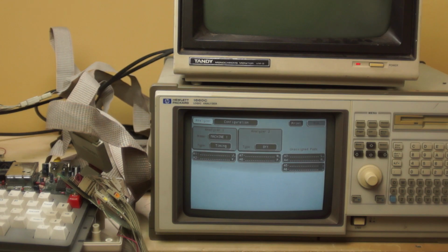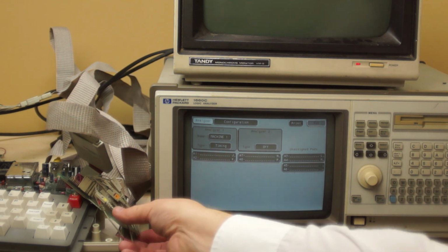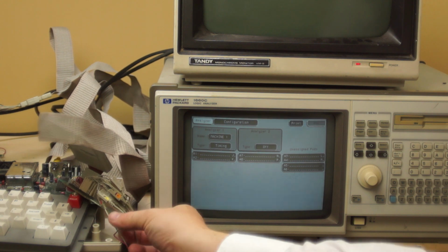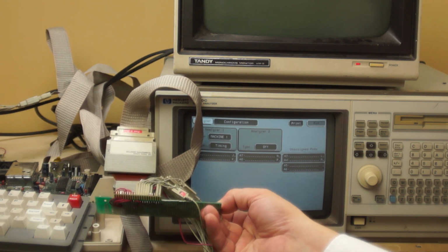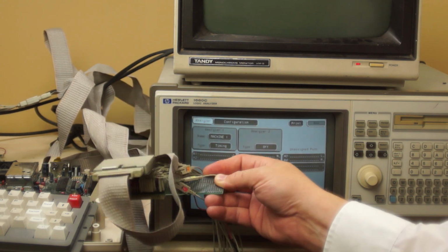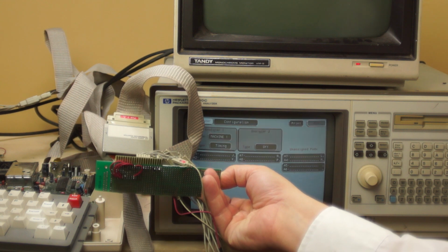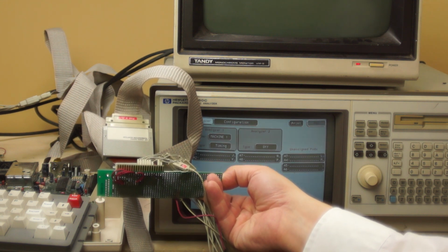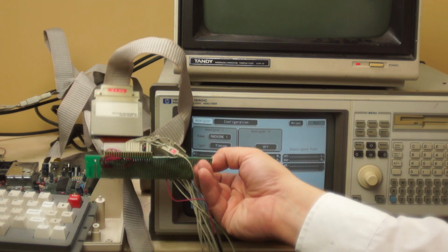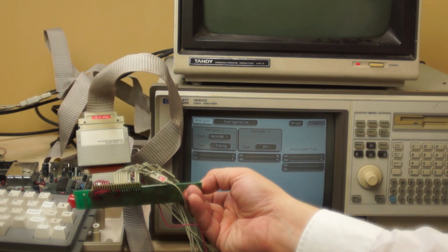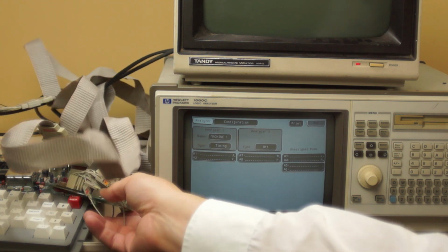We could see from the previous test that the SCS and the CTS lines go crazy when there's a cartridge in the slot. But I want to show you programmatically how you can trigger those lines or how they work. The way I'm going to do it is I'm going to use another toy, which is the logic analyzer, and I'll use this little breakout board that I made. It's not beautiful, but this allows me to plug into the cartridge slot of the Coco, and I can see the address lines and the data lines on the Coco itself, so I can basically monitor what's going on. So let's plug this in and see how we can trigger the SCS line.